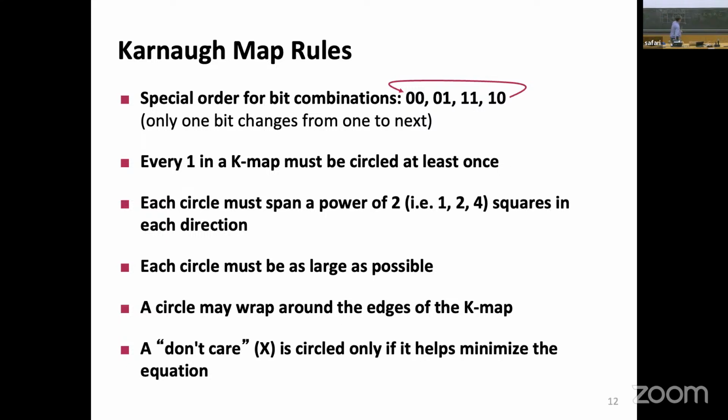Let's do this. I like it. Why not? So what's the function? Anyone who wants to start? Let's try with this one. Okay, so let's see. A is 0 here. B is 0 here, B is 0 here. So this means not B. And here, in both cases, C is 0, so not C. Right?